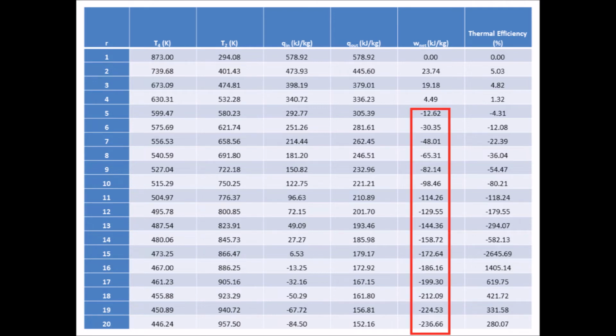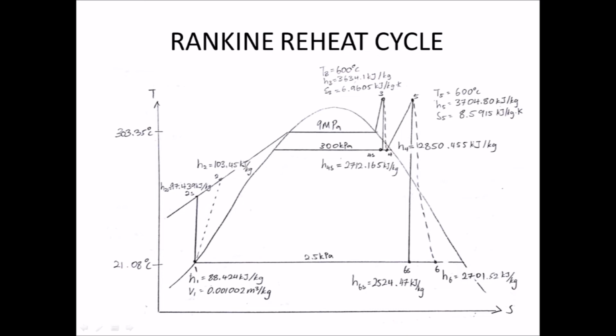As pressure ratio, R, increases, the work net drops below negative. The best efficiency the Brayton cycle can achieve for this parameter setting is by using pressure ratio close to 1 with efficiency around 0 to 5.51%.